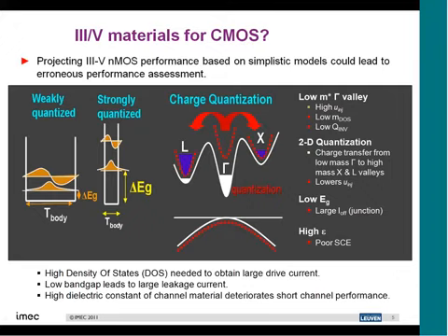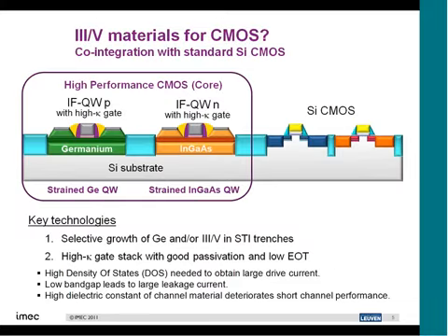So for example, this is a typical band structure that you see for gallium arsenide. You see that here you have the very sharp edge, so that the second derivative gives you a very low effective mass, but you also have pretty low density, and pretty soon your carriers will fill up these other valleys that have higher effective masses, so you cannot carry that much current. So in order to have a good material, you need a combination of high mobility and high density of states. So that's why it's not always obvious to just go to a high mobility material.